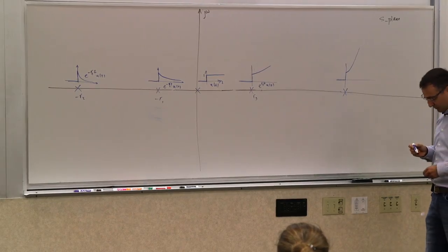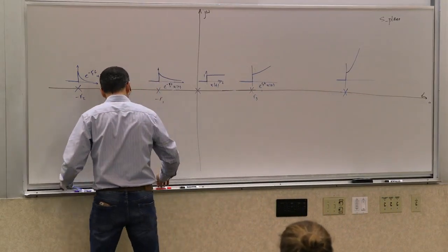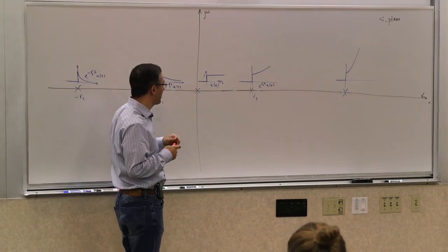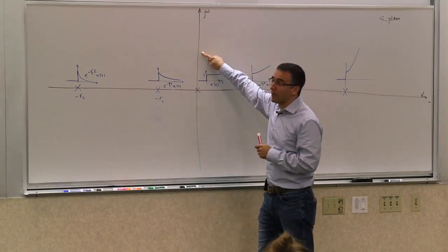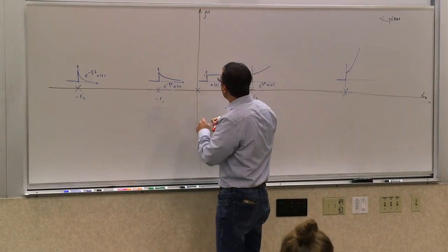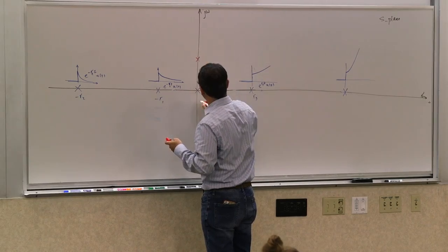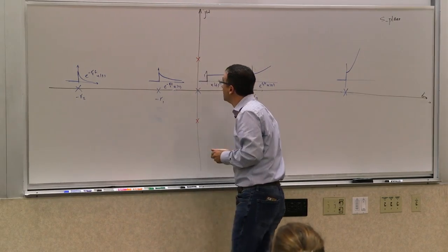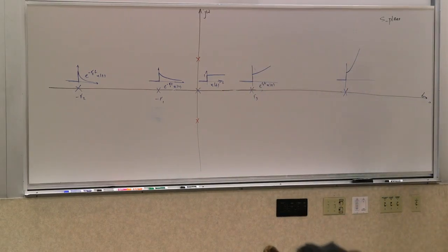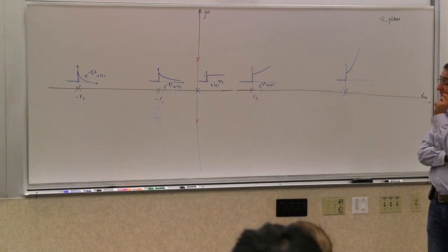What if I had complex conjugate poles? Let's say imaginary poles. Right? First start with imaginary poles. Poles on the j omega axis. Obviously I can't have one, right? So I can have a pair of poles here. So this is really a second order system because it has two poles. What is the impulse response of the system if I just had those two poles?